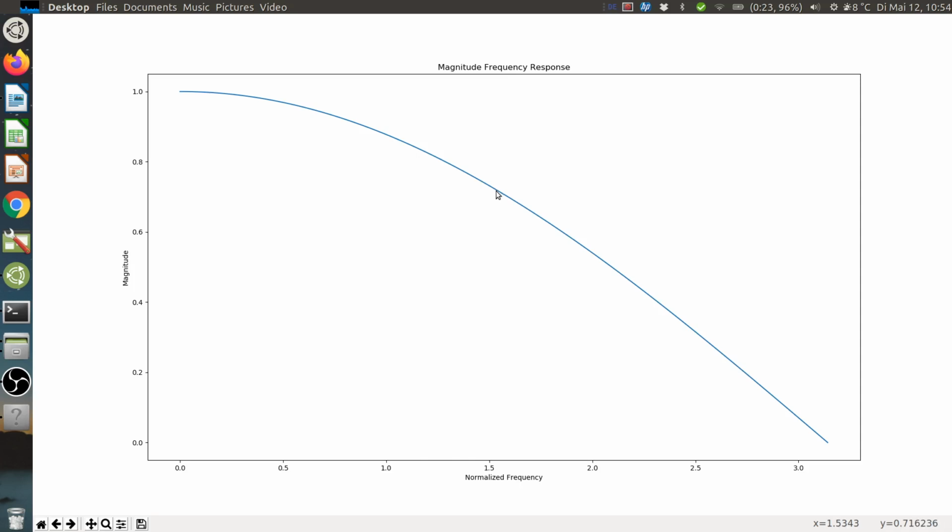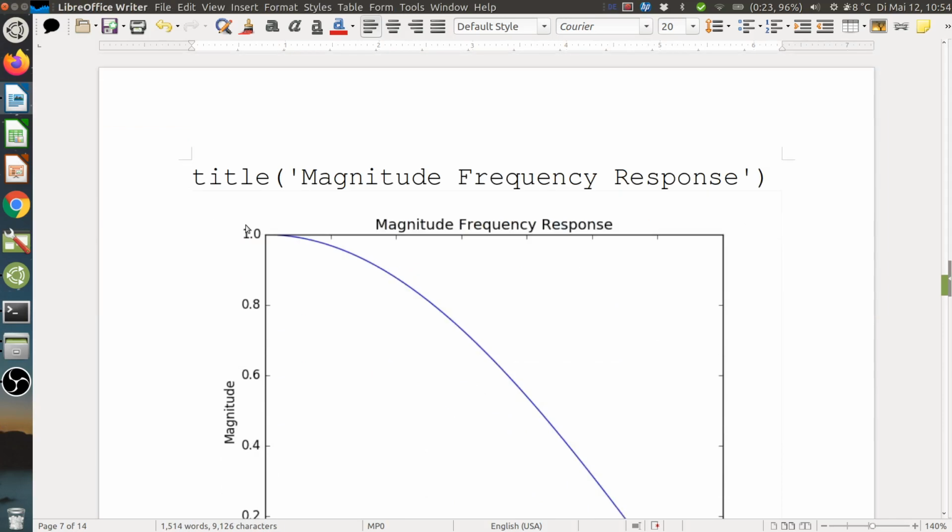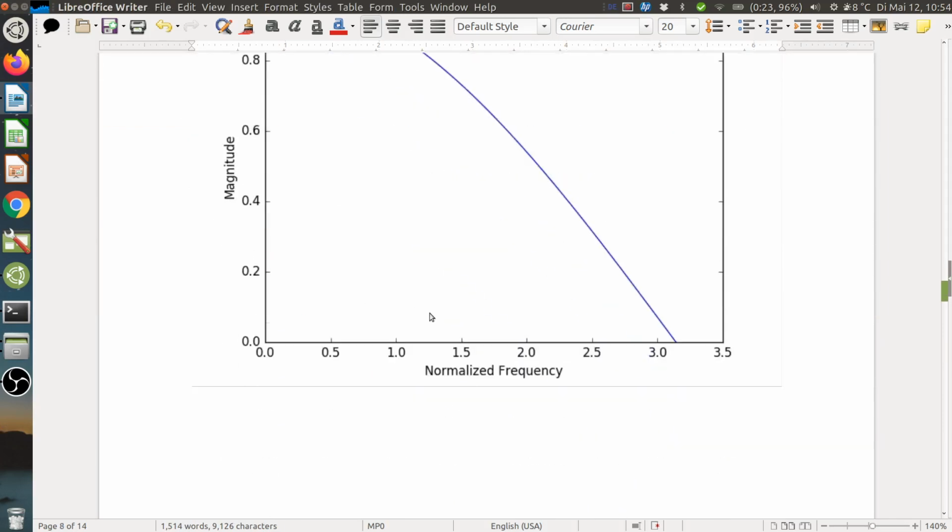Here you can see that those sinusoids become attenuated a little bit, but not really much. It's only when you come close to Nyquist frequency, so down here, so here I'm very close to Nyquist, then I have a much smaller factor. So only right in the end we have a good low-pass filter. Right. Yeah, so this is what we see here again.